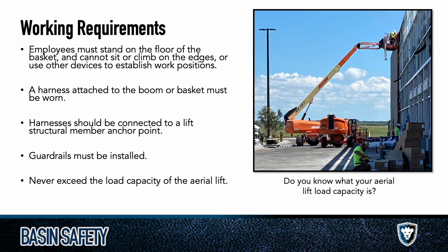Working requirements. So you've got to stay on the floor. You can't step up on the handrail. You can't jump out of the thing. You don't want to, as in our first photos, step over to something. You want to stay in that thing at all times. You can't be standing on a box or anything on the floor. You want to make sure that you're tied in. Sometimes they can be a little goofy, like the anchor point, so make sure you're attaching to the anchor point and not to the handrail or the guardrail. That is not the anchor point.